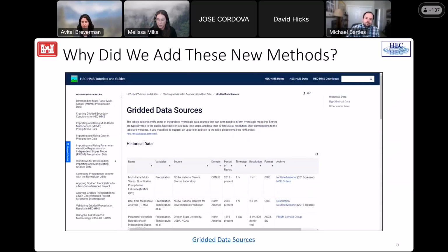So let's talk about some of those data. There's a ton of gridded temperature and precipitation data sources that are available for both historical and future time periods. But it's important to note that gridded precipitation and temperature data sources are often provided at a daily time step. A couple of these common data sources are LIVNEH and AORC. There's one LIVNEH unsplit data source that is provided at a daily time step from 1915 to 2018. So that's over 100 years of coverage on the LIVNEH data set.